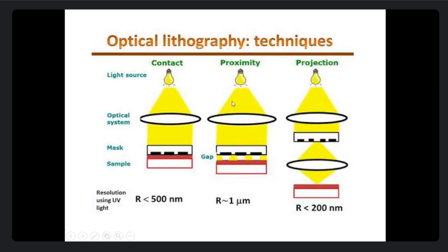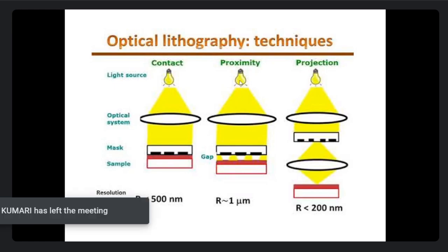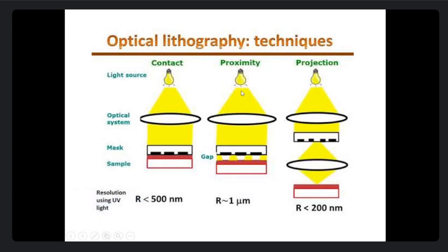The second possibility, the most attractive one, is the reduction of wavelength. So you have to replace your light source, say from UV to DUV, and maybe from there to extreme UV, which is another solution people are using nowadays. Extreme UV is very, very popular. Anyway, the main point is that you have to reduce the lambda.